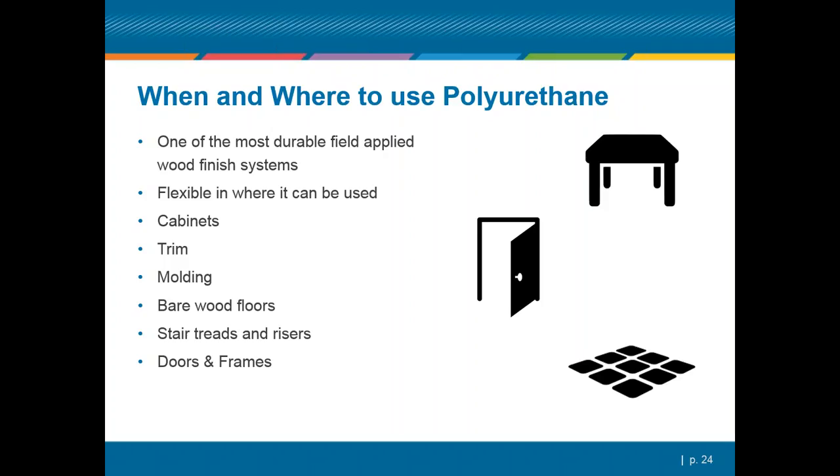But the moisture-cured urethanes come in a pigmented version as well as a clear version. And that makes them extremely durable because of that cross-linking aspect of things. They can put up with some of the wear and tear that maybe some of these single component products would not be able to come close to holding up under. But if we need to talk about moisture-cured urethanes and so on, we can do that as a sidebar and certainly get you some information about those if you have need for that.